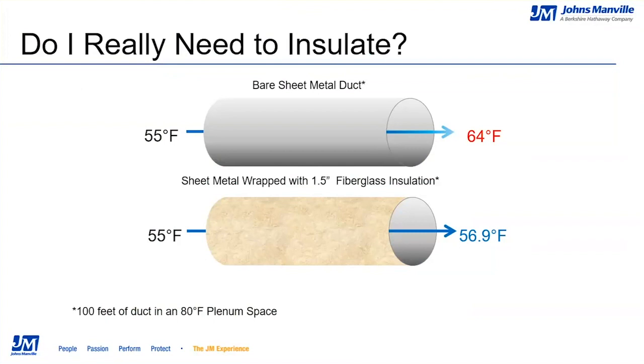That being said, the simple answer to the question of whether or not you should insulate is yes. As you can see from the graphic on the screen, if you have a duct in an 80-degree space, the cool air in a non-insulated duct will rise 9 degrees over 100 feet.